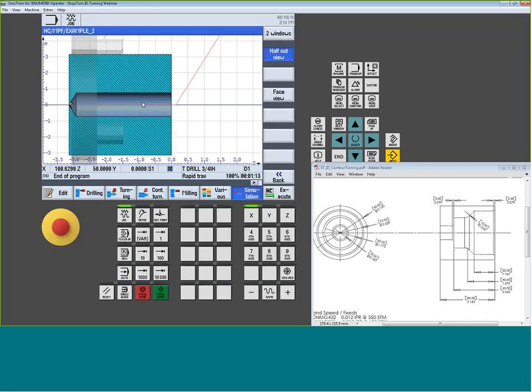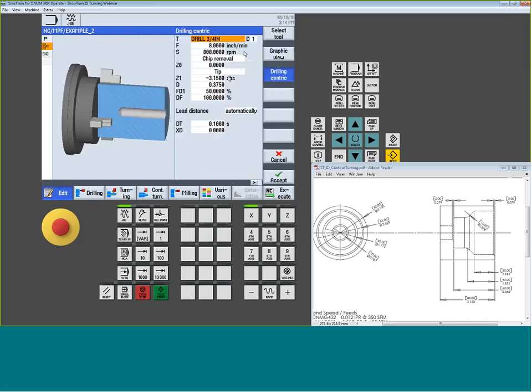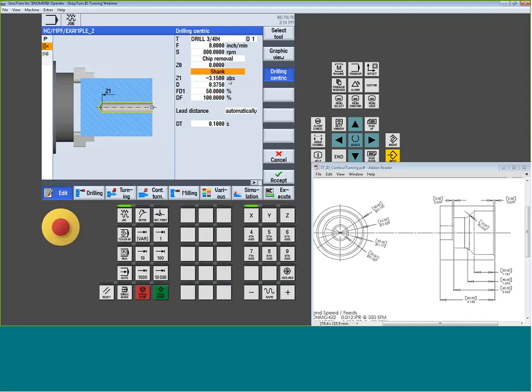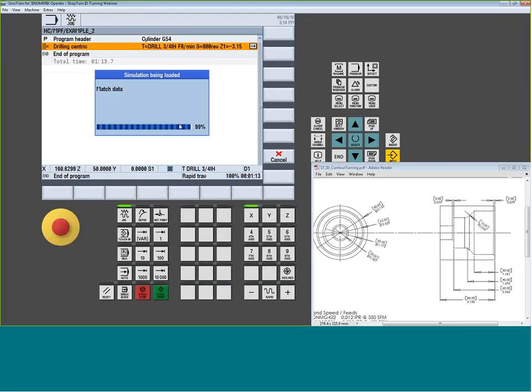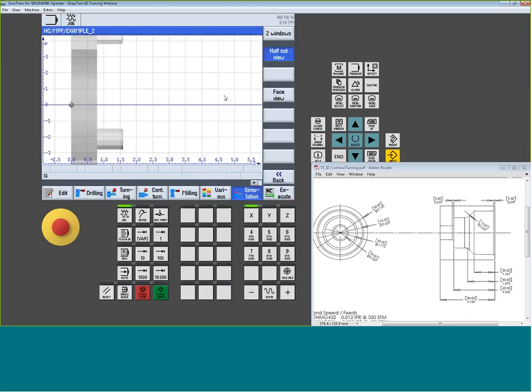All right. So we have our section view, our cut view, and you can see the tip. Well, that was because I told it to drill just to this edge. So if I'm working up the tip, I now have to automatically compensate for whatever this projection of the drill is. That's where our tip shank comes in. The shank will now say, I'm going to go 3.150 plus whatever I calculated based on the diameter and the angle I know from the offset table. And now, in this case, it'll make sure it just breaks through.